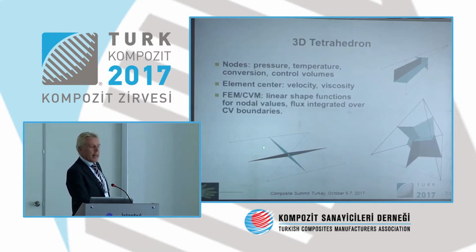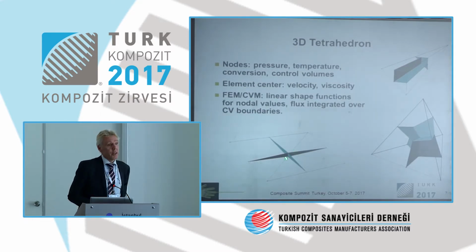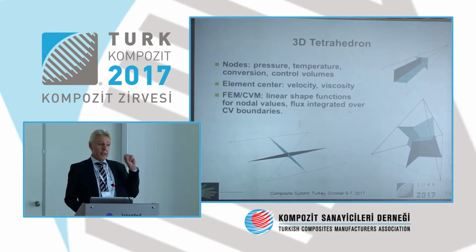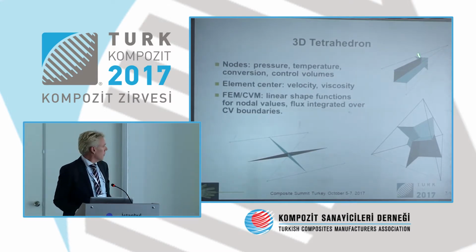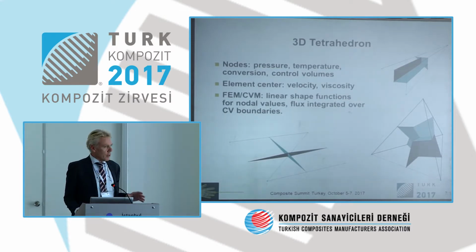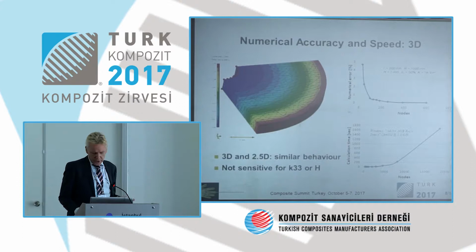And here you see an element which is almost a sliver. That's what we call a sliver. This element gives us the worst nightmares because it's very thin. All the edges have reasonable lengths, but calculating the pressure gradient in the thickness of this element is very, very inaccurate because you are doing it using points spaced relatively far away, and the distance is very small. However, this formulation does not break down until elements really start to have zero volume.